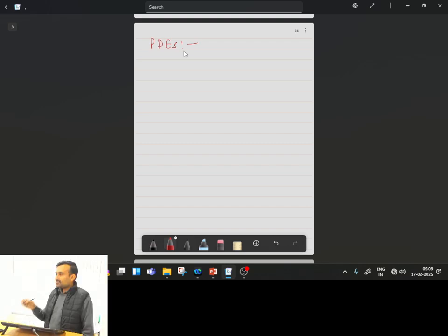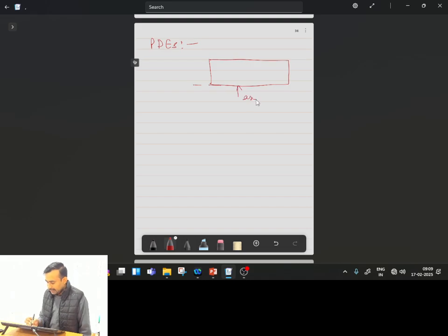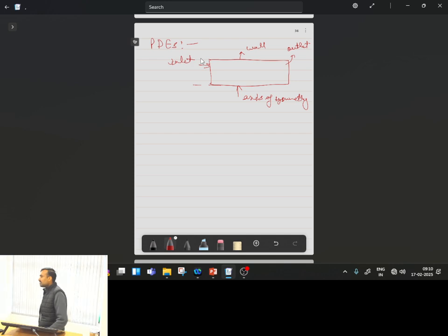Okay, and in case of single phase flow, most of the boundary conditions are clear to us. For example, if we talk about flow through a pipe, we take the axisymmetric simulation domain, and in this domain, if we have to specify some boundary, this will be my axis of symmetry, and this will be the interface close to the pipe wall, and here it can be given as outlet and this can be inlet. So if for this simplified situation you have to give the boundary condition, how can you specify? There are different ways to specify boundary conditions.